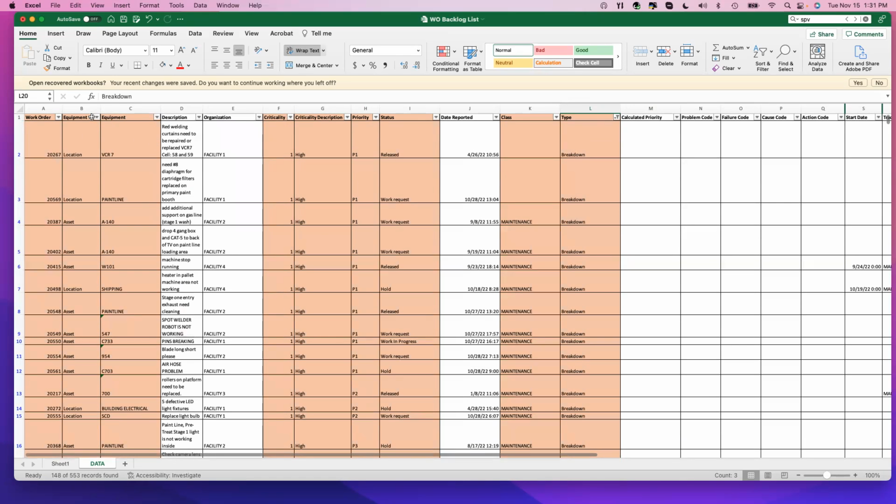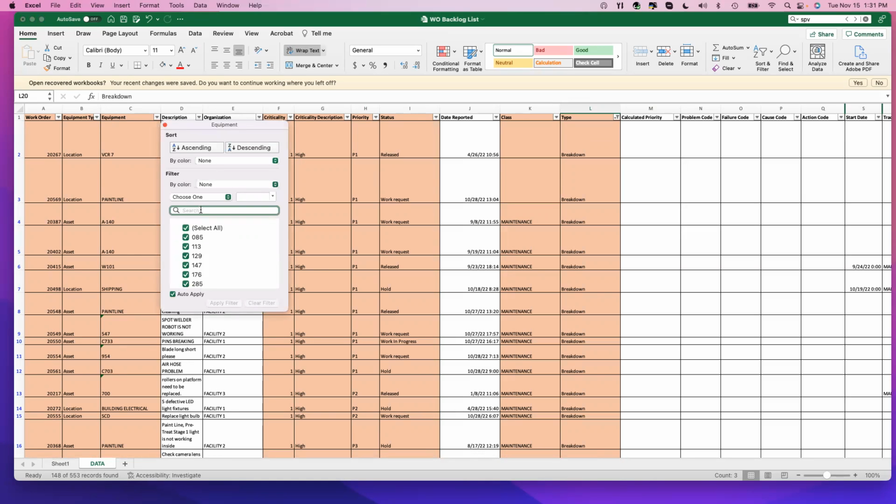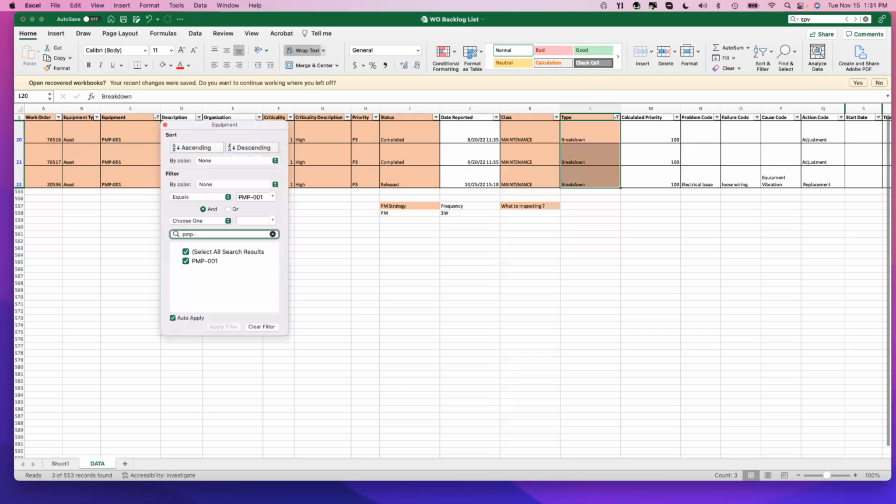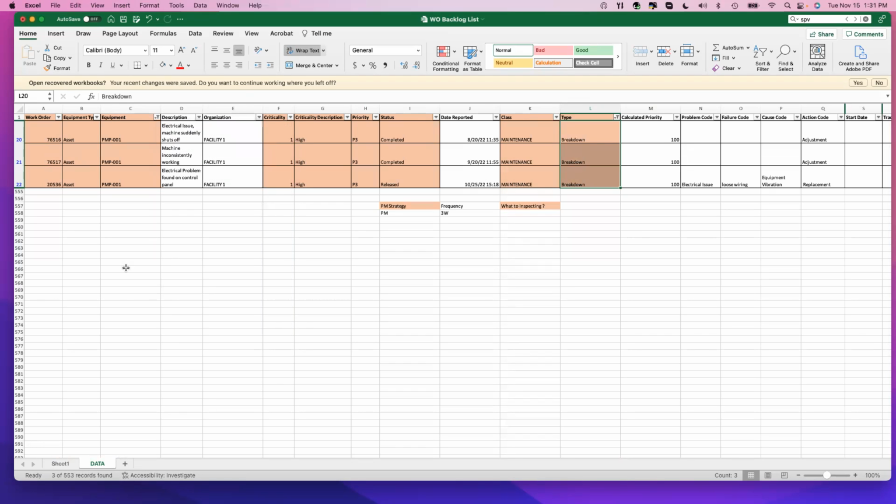Does that answer your question, Ernesto? Yeah, so I guess to recap, you would say first go with criticality, then follow with whatever the order would be on priorities, and take into account things like the work order type, just to remove preventive or something like that. That it's a kind of frequency-based maintenance instead of just having things that are corrective work orders that happen because something is wrong at that point.